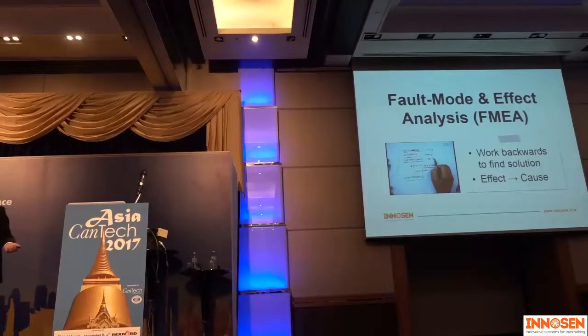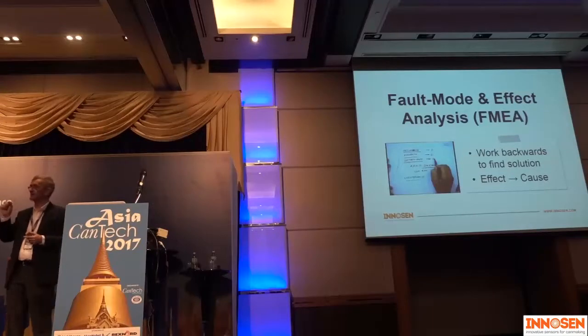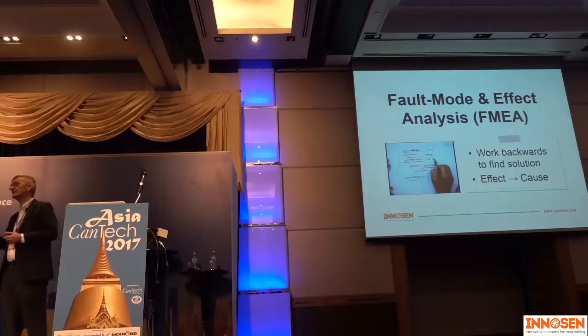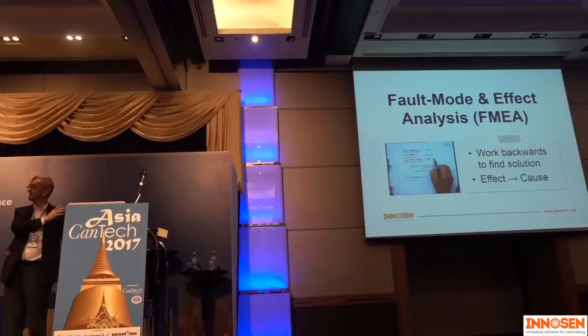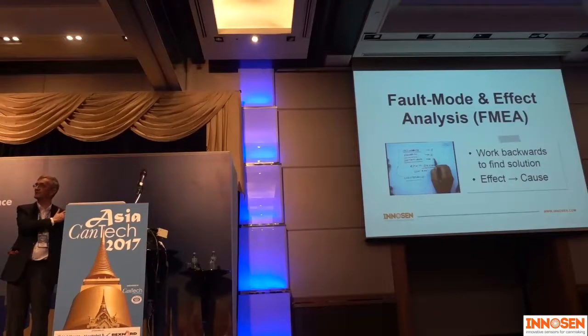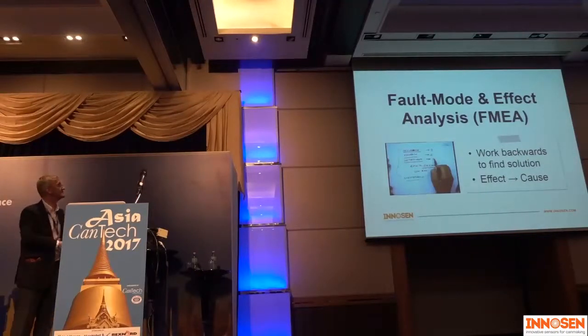This is typically what vision systems are used for. This is typically what specialized sensors are used for. So instead of keeping on going forever and wasting your money trying to get the last 0.00% of faults out of your line, give up on it and invest your money in a gatekeeper, because the return on that investment is actually going to be higher.